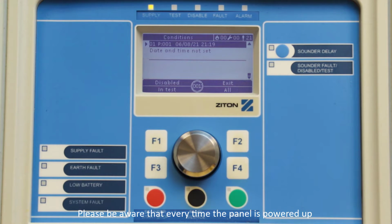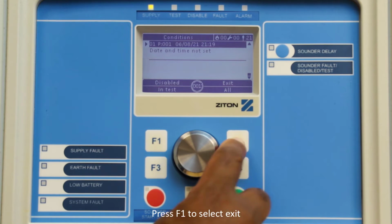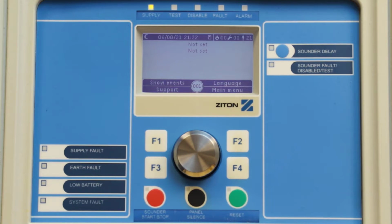Also reported is the time and date has not been set. Please be aware that every time the panel is powered up, you must always set the time and date, or the panel will always display this condition. Pressing F1 to select Exit will exit out of this menu. So, let's now set the time and date.